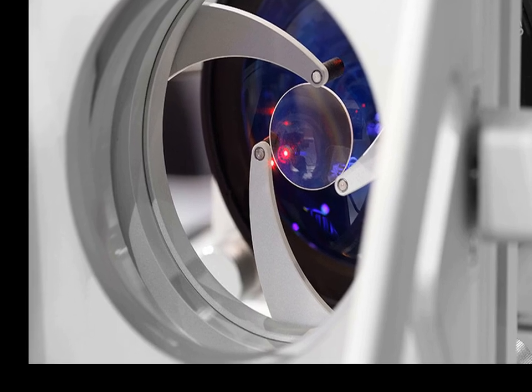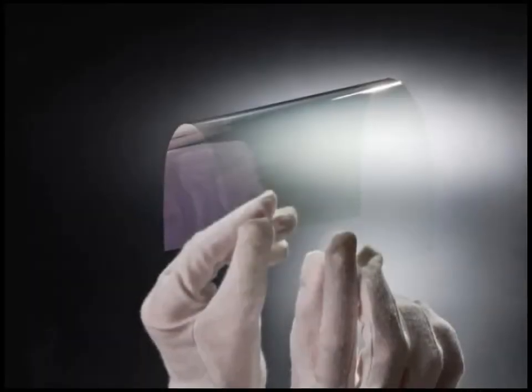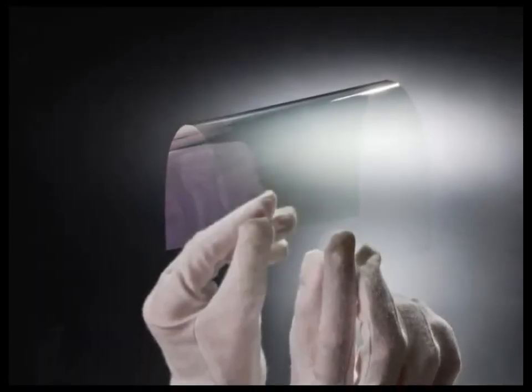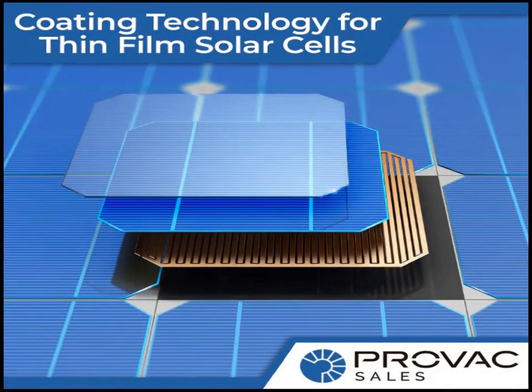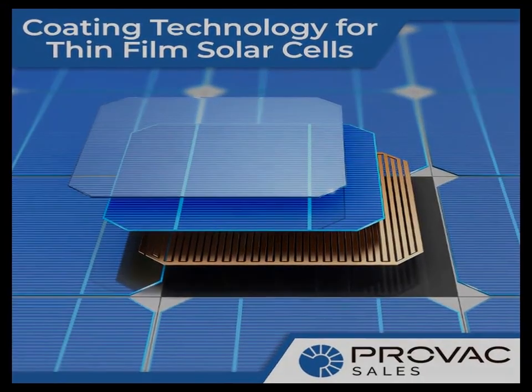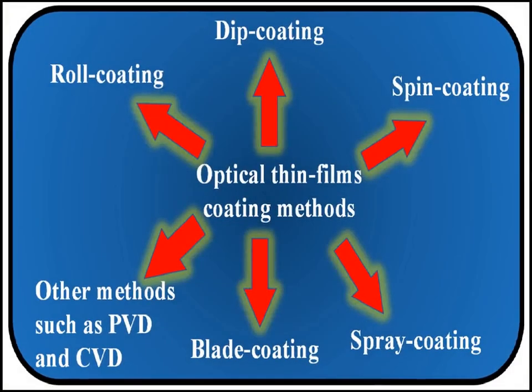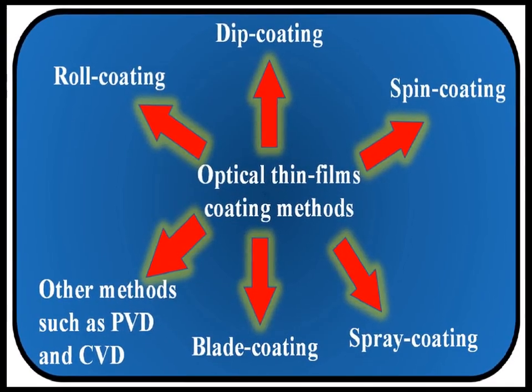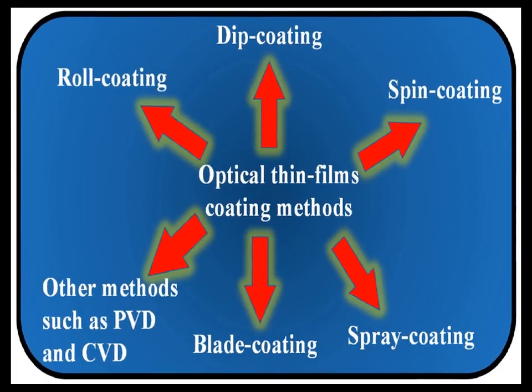Energy applications are equally important. Photovoltaic technologies such as CdTe, CIGS, and perovskites use thin film absorbers optimized for light harvesting and defect control. Thermoelectric devices employ Bi2Te3 and Sb2Te3 thin films, while batteries benefit from ultra-thin coatings that stabilize electrodes and solid electrolytes like LiPON for microbatteries. Mechanical and protective uses include hard, wear-resistant, and low-friction coatings.